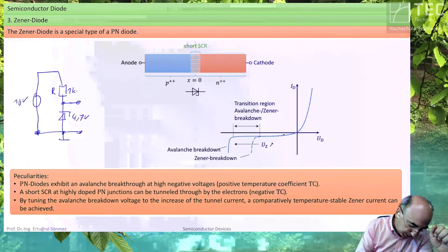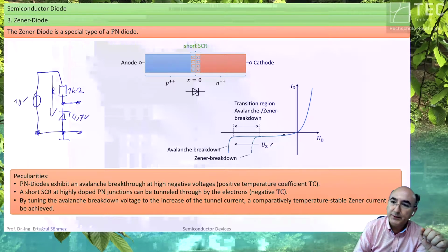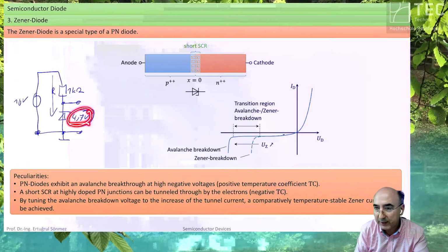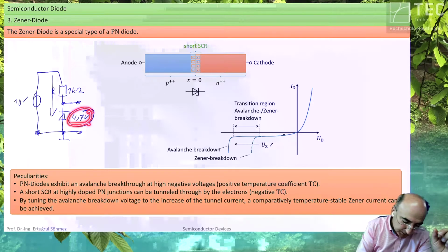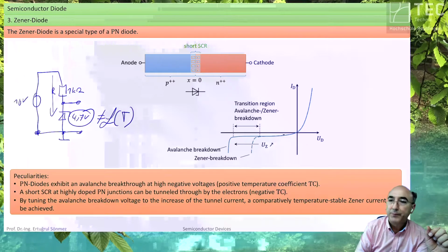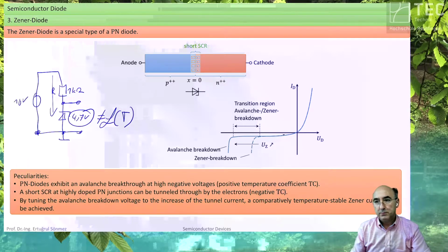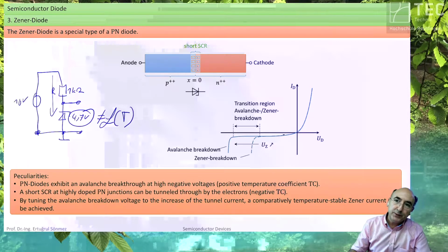You take here 1 kilo ohm, so that a certain amount of current does flow. And the breakdown value of 4.7 volt, if it is designed to 4.7, keeps constant and is not a function of the temperature. That's the purpose of using a Zener diode. Yeah, that's it. Voltage source. If you need a voltage value, you make it this way as the most simple way.